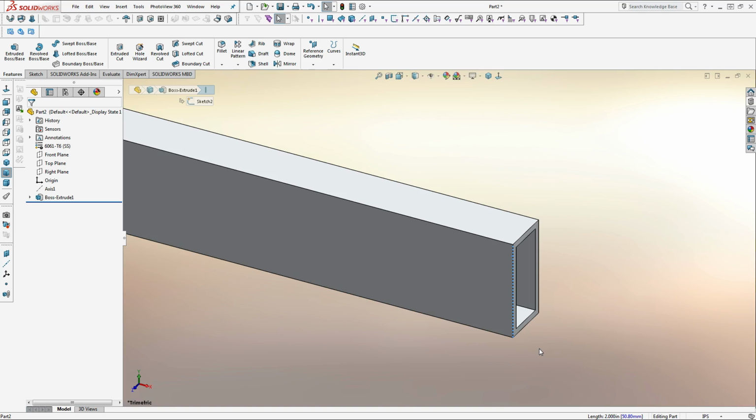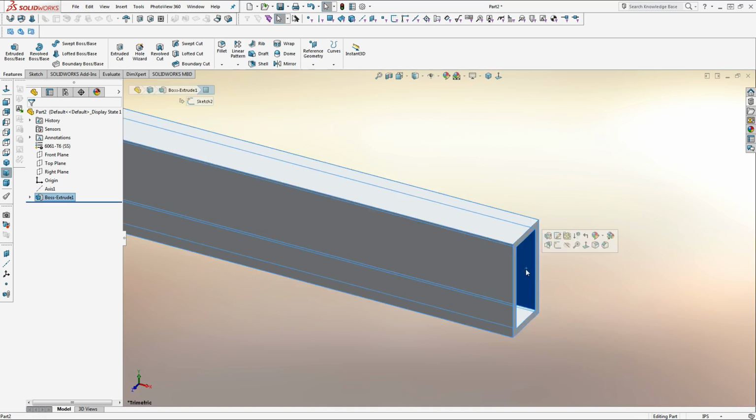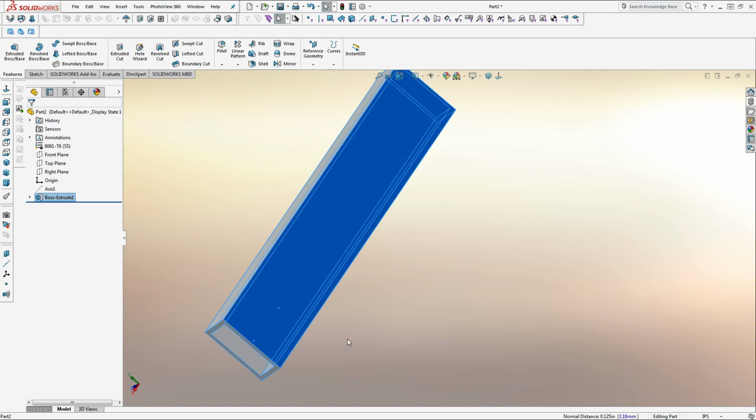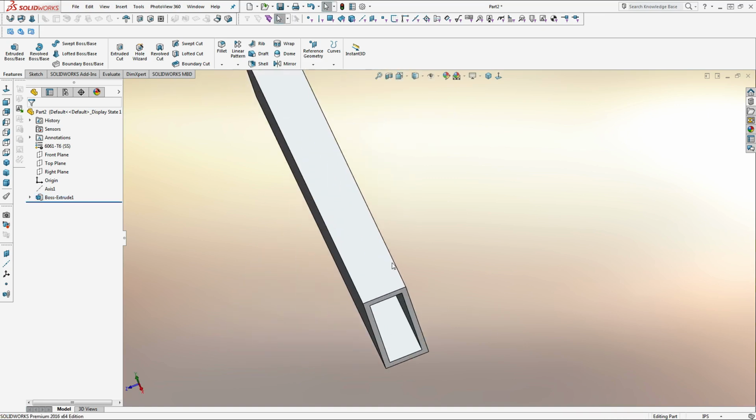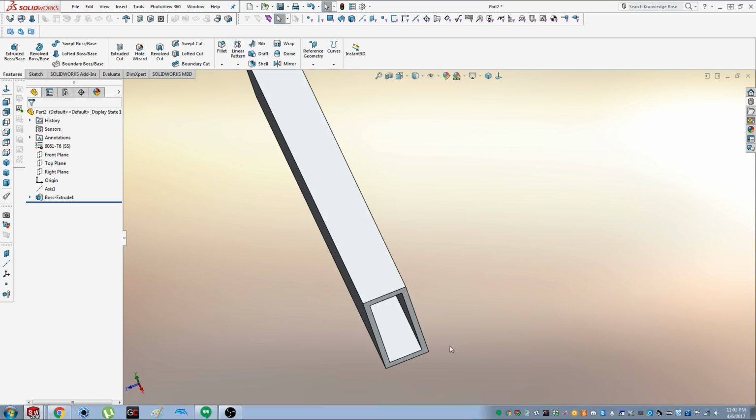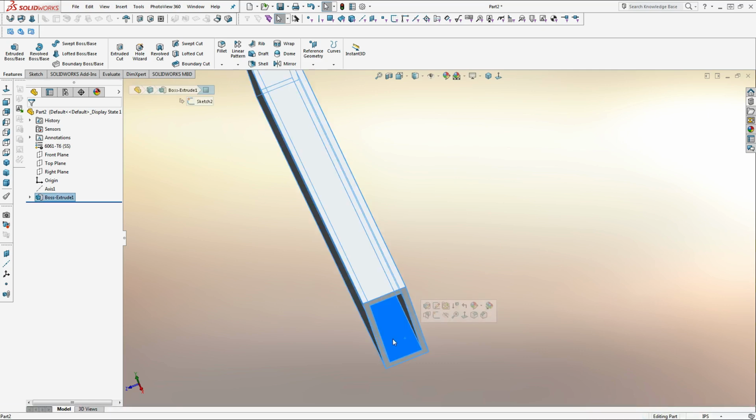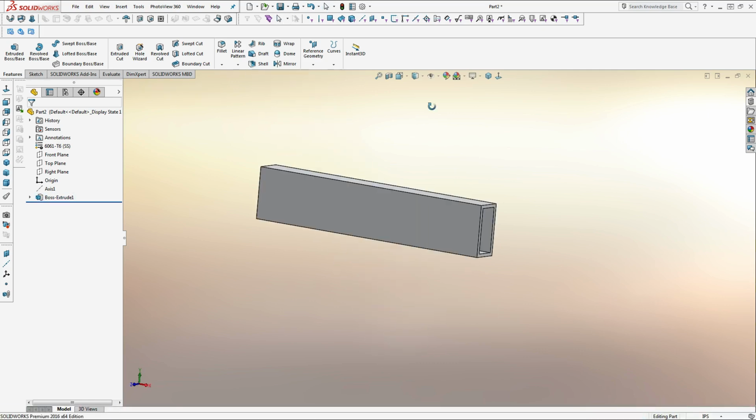And click the side. I'll see down here where my mouse is. Length, oh, whoops, it is. Length is 2 inches for the height. If I select that line, length is 1 inch, so I know my part's right. If I want, I can select an interior face and an outer face, so the normal distance is 0.125. It's an easy way, it's all down here. Easy way of figuring out what dimension something is.